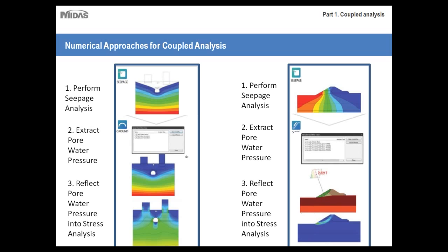Whereas if you have the numerical modeling program, everything is much more seamless. As you can see, this is a screenshot of the engineer importing the loads directly into the slope stability analysis. Here we ran a limit equilibrium method slope stability analysis along with a strength reduction method analysis, which is a sort of finite element analysis. So those are just the basic principles of coupled analysis.